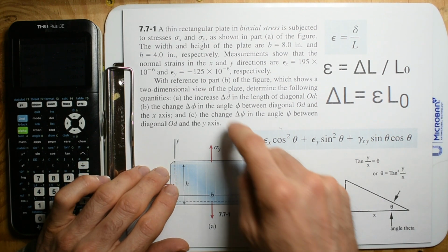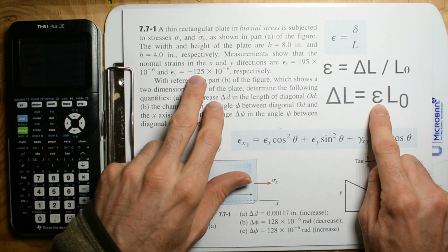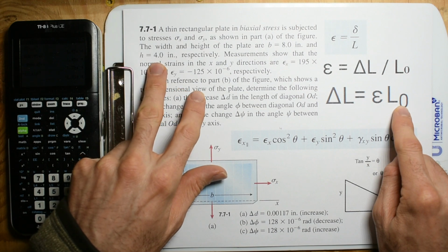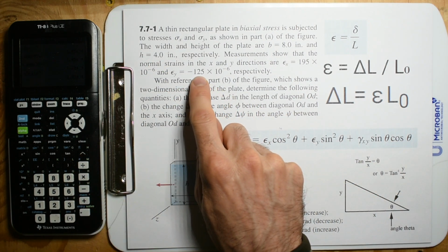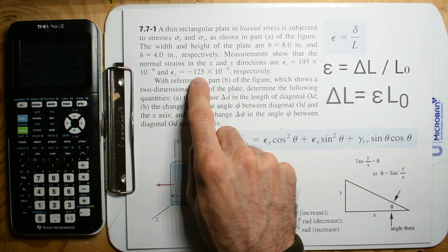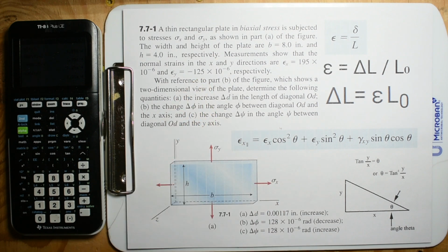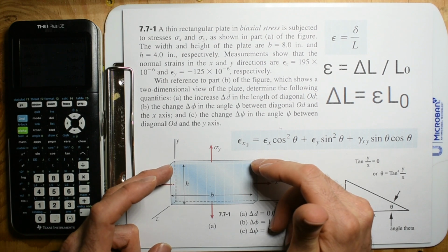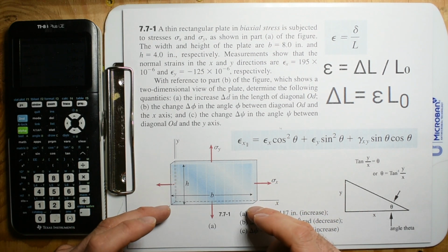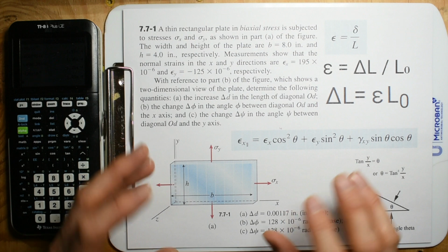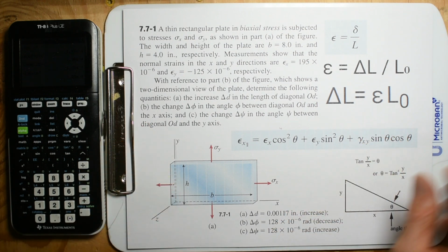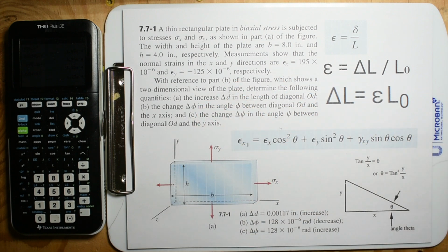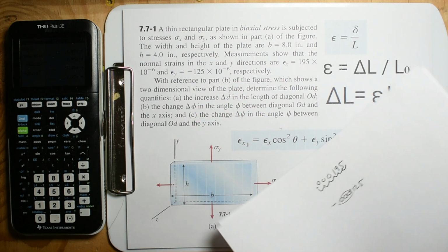Now in the y, we're going to have the strain in the y is negative 125, and then our initial length is 4 inches. And so cool. Let's double this first to 250. Double it again, so we got 500. All right, so we're going to be going down 500. Our change in length is going to be 500 this direction and 1600 this direction. So that kind of gives you the proportion. Now it is good to be like, well, we should know exactly how much this is going to change in length. So let's do that.